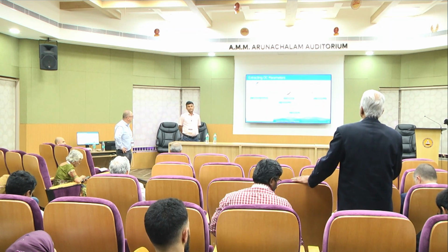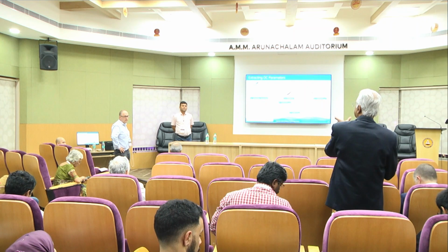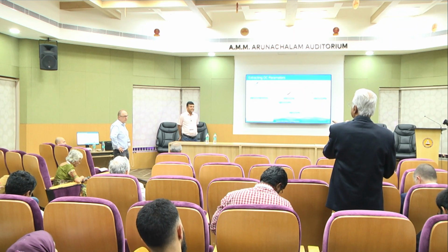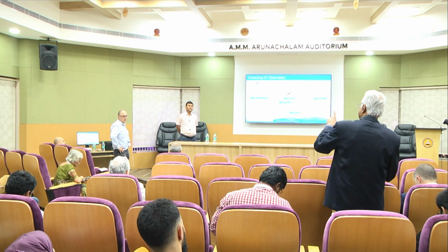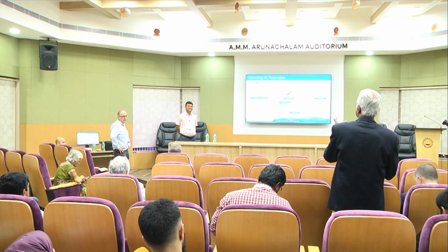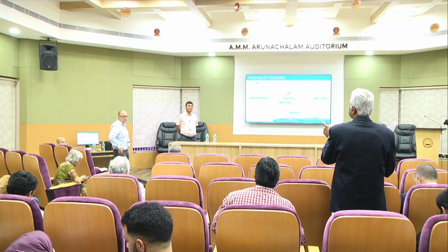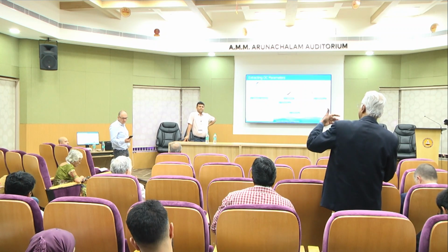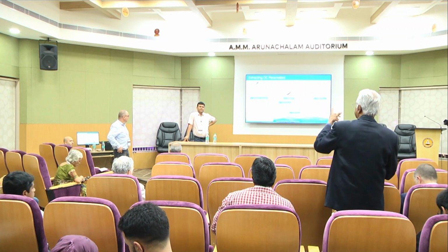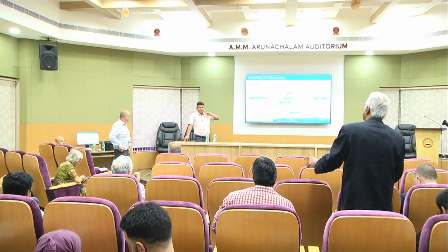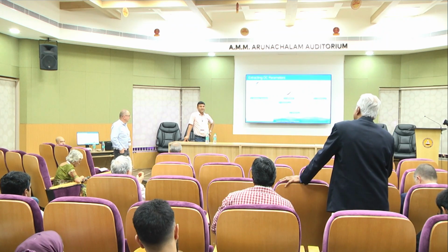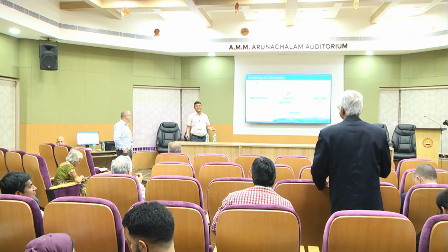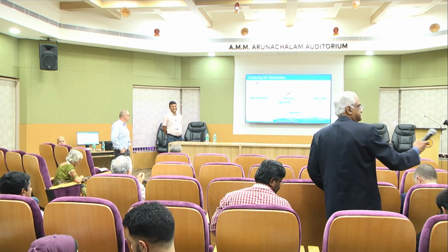I don't know, with the load pull you have tuner passive, no? That's not active load pull. Okay. So if you have one device, transistor device, you cannot obtain the optimal impedance for the PAE, I think. Are you talking about going towards the corner of the Smith chart? Yeah, of course there is a limit. Yeah. Okay, thank you.